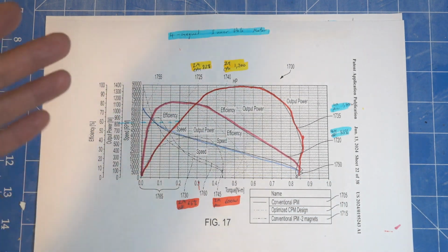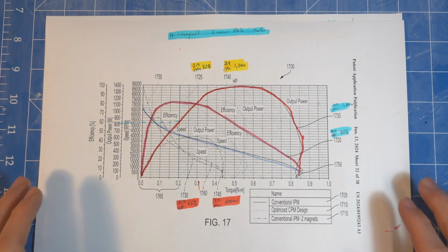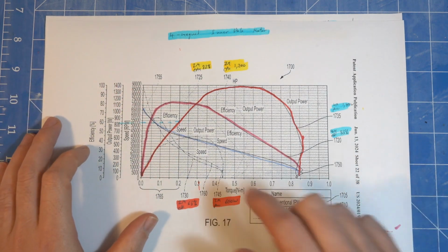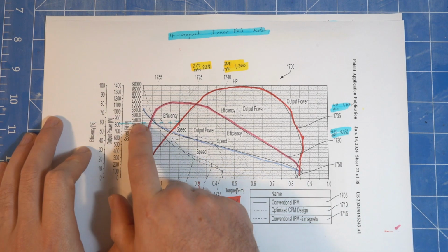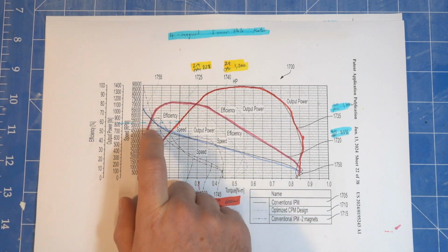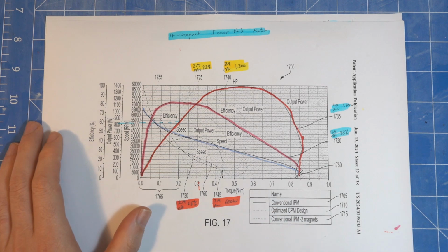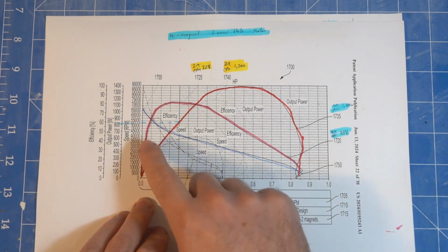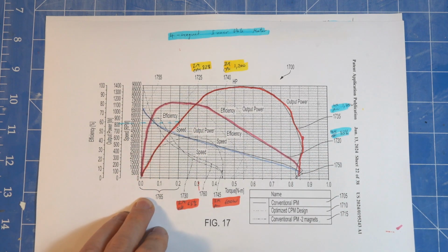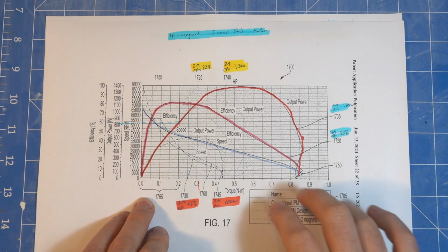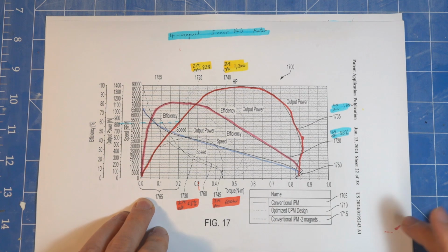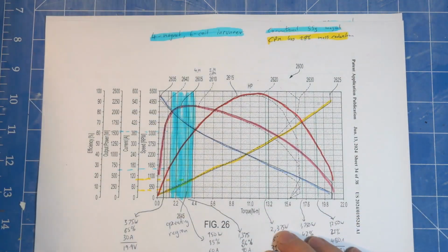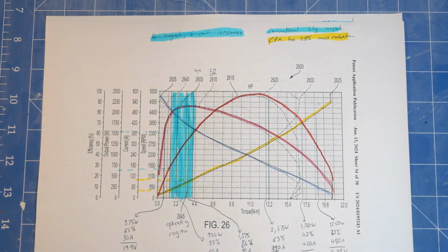And that's the efficiency of their motor. That doesn't factor in, once you go through gearboxes and whatnot, any sort of gear reductions. You can imagine this thing here is definitely getting some gear reductions. And also, I think power loss through the wires, because I'm pretty sure for their efficiency, they're measuring it very close to the motor, not factoring in power loss through the wires, which we'll see in a later graph. Well, this graph actually.